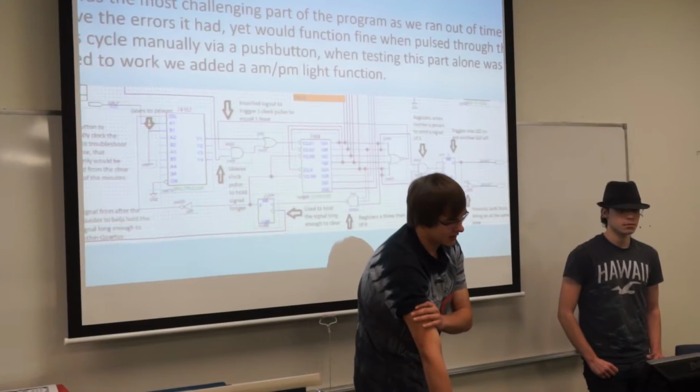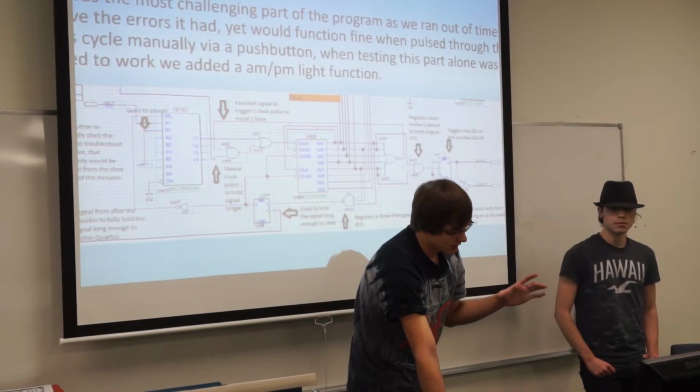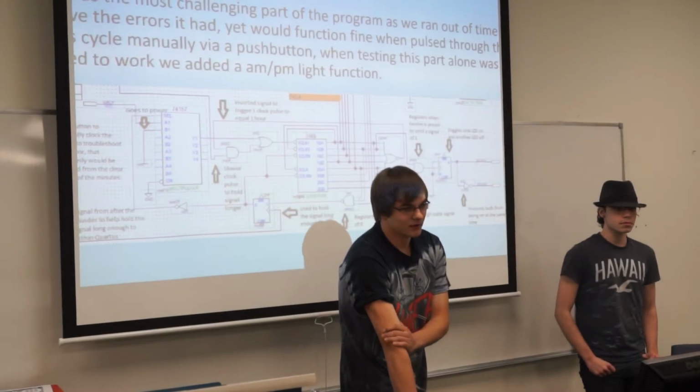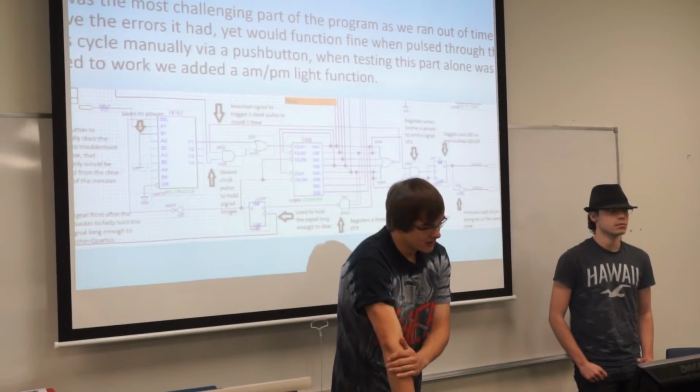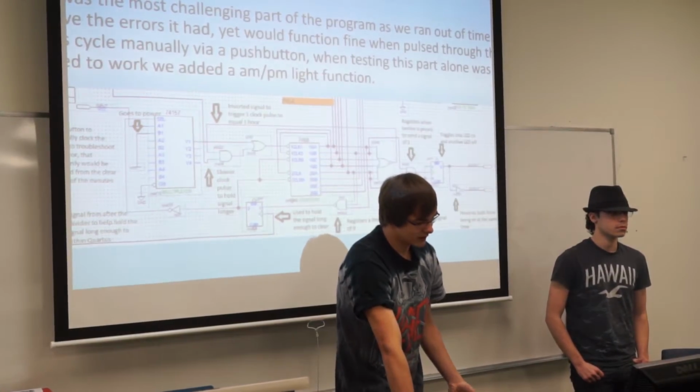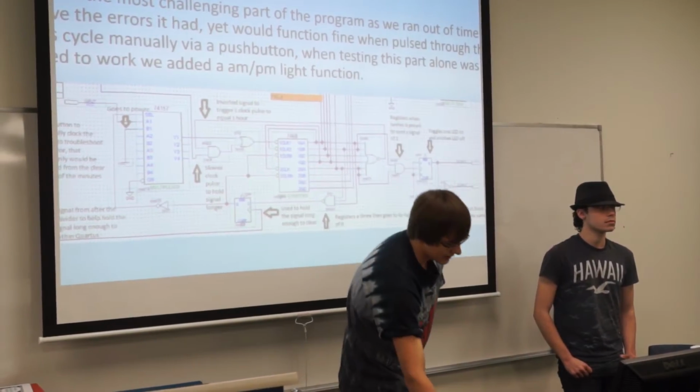The hardest part about the clock, in my opinion, was that when it cleared from 12, it would go to 0 naturally, and you don't want that. You want it to go to 1 o'clock. And that was a very tricky part, trying to get it to clock one additional time. When it cleared, it was just having all sorts of timing issues.